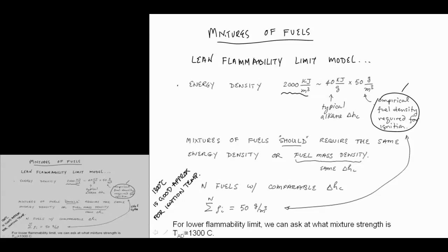So we have a room where somebody was storing gases and somehow there was a release, and in this room we have methane and we have propane. Now the lean limit for methane, we found out, was 5%. So this is for CH4. The lean limit for propane from that page is 2.1%, okay?